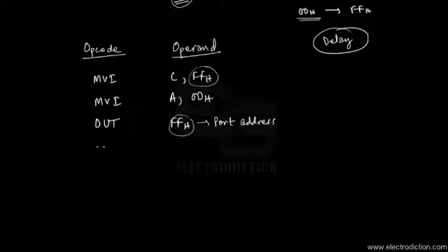So what we do here is that we write DCR C. Once the output is done, the C register's data needs to be decremented once. So DCR C, and then we're going to give jump on no zero. If the count of the data present in the register C is not 0, then the jump statement would be executed, and this is going to jump to the label J1. So I'm just going to give here J1. So it's basically a label now. I'm going to give the memory address later. So it's going to jump right over here.